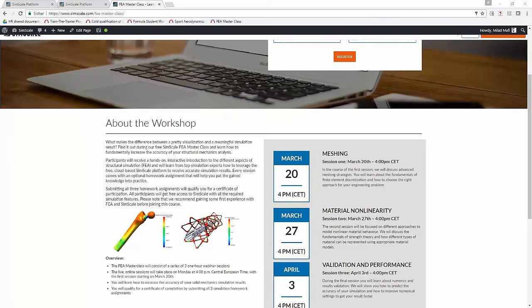Constantinos has a question, to be sure he understood the task of the homework. The goal is to change the mesh. Will it be generated in this model that will be given to us in order to have fewer degrees of freedom? Yes, exactly. We'll provide you with a ready-to-use mesh and the related simulation, and your job is to take this mesh and adapt the mesh size in order to reduce the degrees of freedom while keeping the quality of the results.